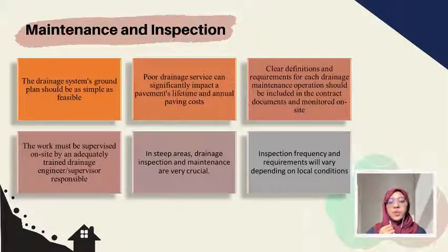Inspection frequency and requirements will vary depending on the local conditions, and the site should be examined regularly every 2 to 3 years. To achieve construction standards, the work must be supervised on site by adequately trained drainage engineers or a supervisor responsible for ensuring the work is built according to the designs.